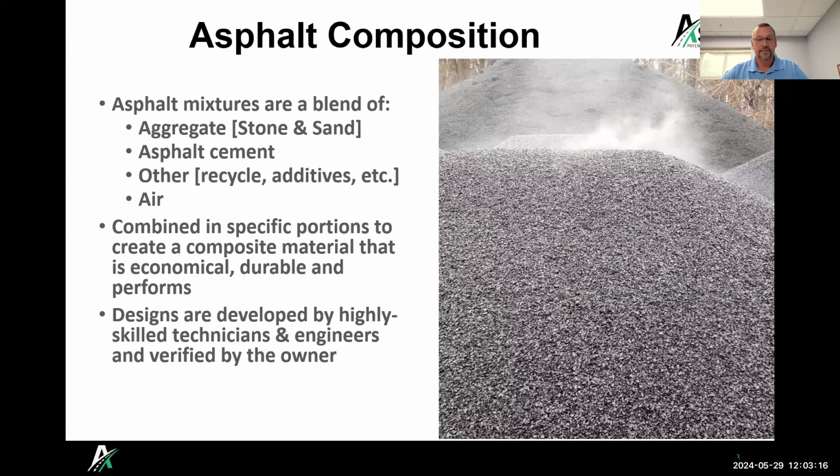They need to be durable, environmentally resistant, and able to handle traffic wear to meet any requirements of the specifications. Asphalt cements are engineered for the application as well. Any other materials, RAP, RAS, warm mix, recycling agents, rubber, anything else that we're putting into the mixture also has to be taken into account.